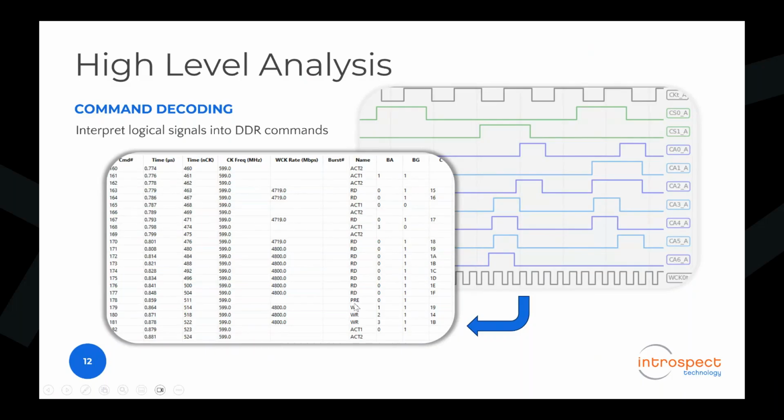And as I will show you later in the demo part of this webinar, you get hyperlinks to go between the logic view and the protocol view, as well as information about the arguments for commands and so on. So the intent is really to increase productivity by giving you as much information as possible about the protocol that's being transmitted without you having to go and analyze the timing diagrams yourself.